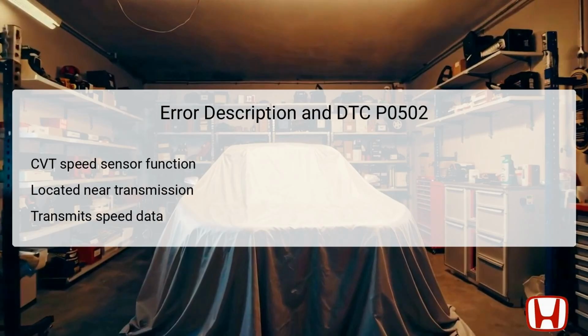The CVT speed sensor is integral to the transmission system. This sensor monitors the speed of the output shaft in the CVT and sends crucial information to the TCM. The TCM uses this data to adjust shift patterns and optimize engine performance. Typically, the CVT speed sensor is located near the transmission housing, making it accessible for inspection. A malfunction in this sensor or its circuit could lead to erratic shifting or poor acceleration, and this is precisely what DTC P0502 aims to address.